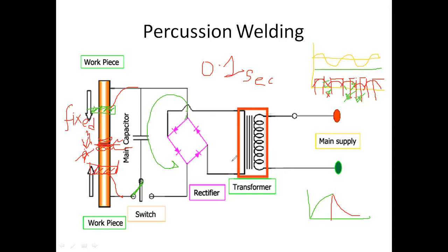The advantages are that it is a rapid process, so very little time and less power are required, and a higher arc temperature is created compared to flash and butt joining. Heat-treated parts may also be welded, the heat is concentrated only at the two joining surfaces and not other portions, and dissimilar metals can be joined.